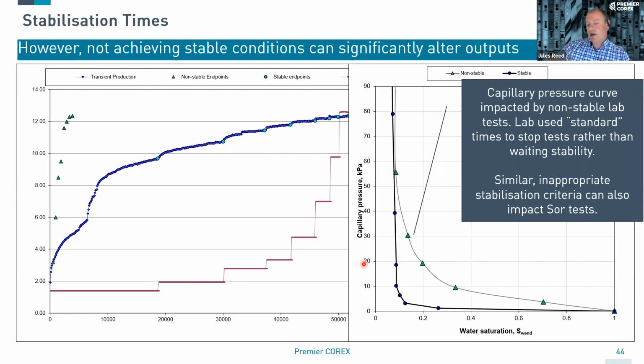So what you have to do in those cases is you determine the saturation in the core. You also determine the saturation of oil in the fluids outside the core, in the sponge or the pressure barrel, and then make a correction, because those would have been in the core, and they've been pushed out as gas has expanded as you bring it to surface. But generally they tend to be pretty accurate if everything has gone well.